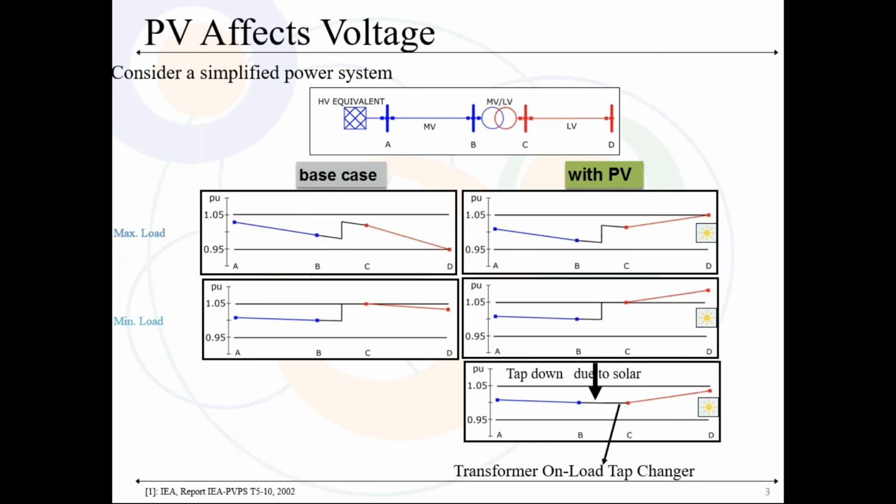In the United States, the voltage is required to be within 5% of what we call 1 per unit, which is basically the nominal voltage, whatever it may be in a given distribution line. Other countries it may be slightly different, and certainly in some developing countries these voltages may fluctuate by much more than that. But these are our standards, and utility is required to maintain that range of voltage.